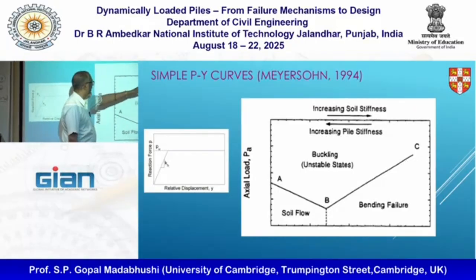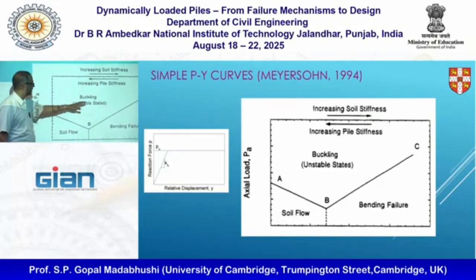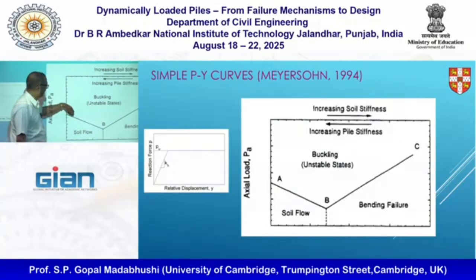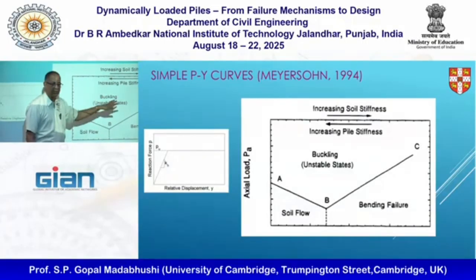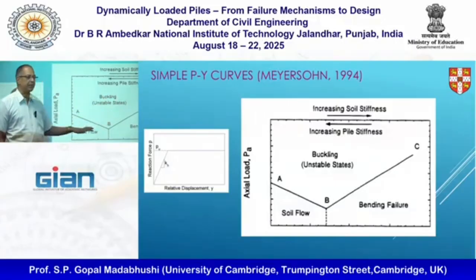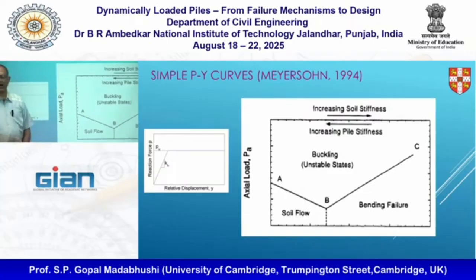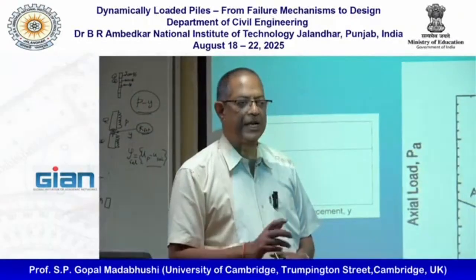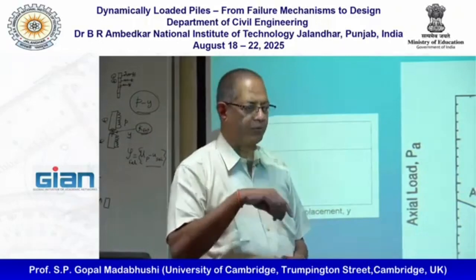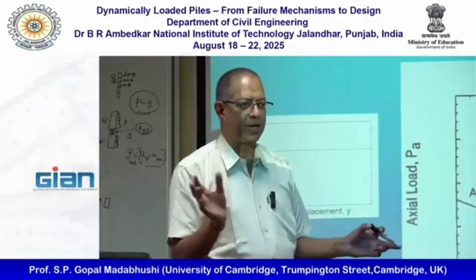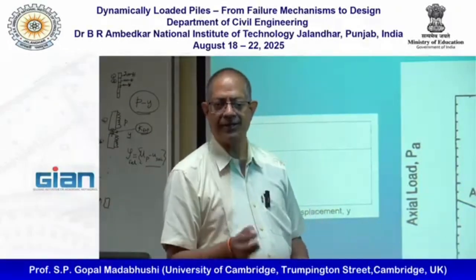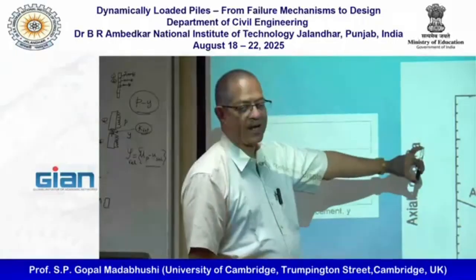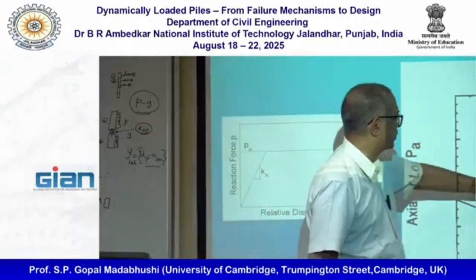Whether soil stiffness or pile stiffness, you will always find in this space piles will buckle. How big this is depends on the pile stiffness, but also the end conditions. Is it a free-headed pile or fixed-headed, pinned, whatever the structural joint is, that will determine the magnitude, but certainly it will be in this space.